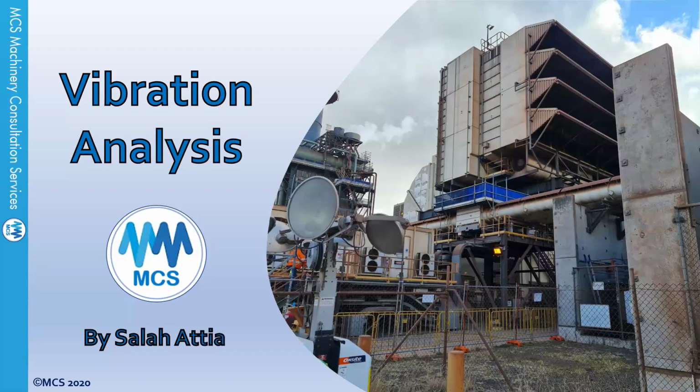In some situations, if you have casing distortion or pipe strain, it can also increase the 3x vibration in the pump. I'm not sure if this pump has wear rings. That could be the reason. Wear rings can also cause something like that. Many situations can cause an increase in the 3x vibration.